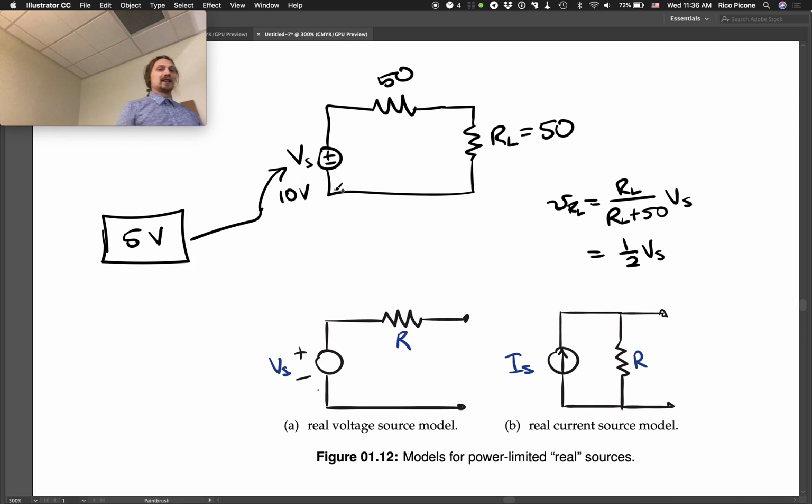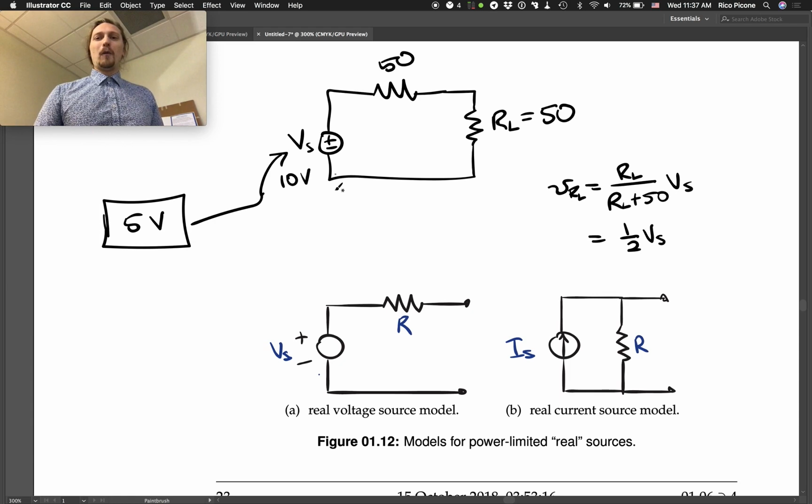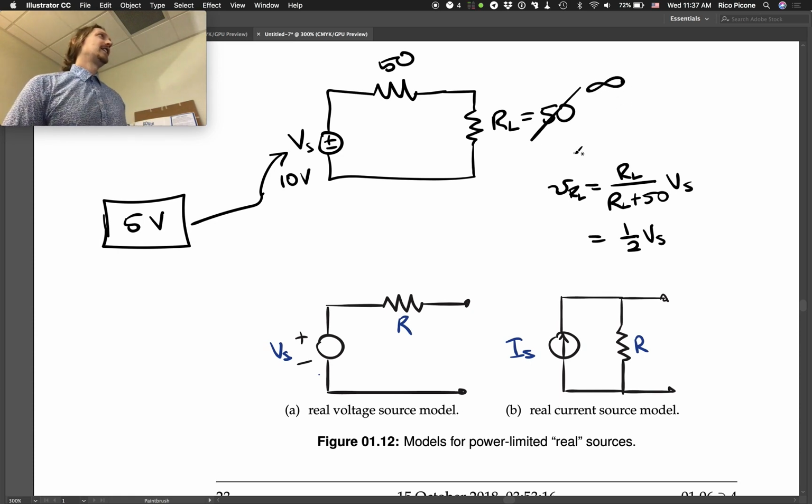That it's going to assume you're going to put it across a 50 ohm load, so it's going to give you what it assumes you're going to need. Now, we very rarely do put it across a 50 ohm load, right? So if we put it across a high impedance load, so if RL is, instead of 50 ohms, is large, then this is large over large plus a little bit, which is effectively 1, right? And the VS is what we actually see. So this would equal VS.